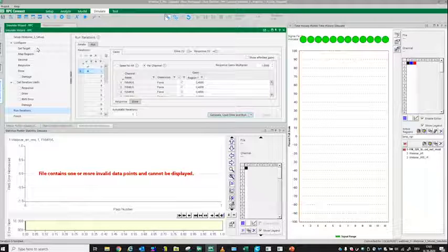So if you have seen something which is wrong in your target file, you had some wrong channel order or whatever is occurring, you can just go to set target, and then RPC will ask if you want to continue the iterations, depending on some restrictions, of course, but depending on the iterations, you can continue from the step where you were. Okay, back to the question.